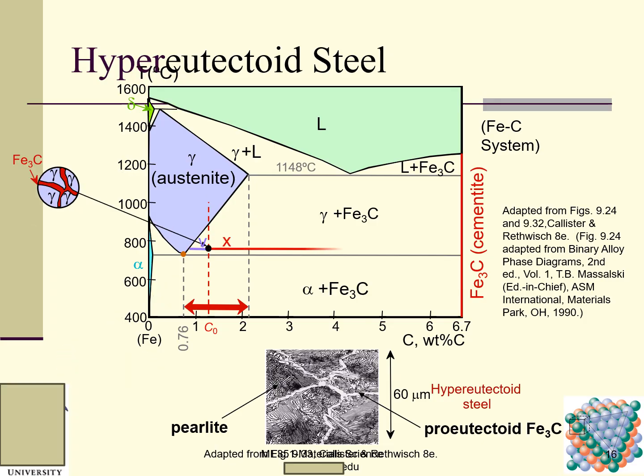And so what we want to do is the weight percentage calculation, and we use the same lever rule here. So you can use this equation to calculate. The gamma is x, right? The numerator is x. We need to be very, very careful. For this point, we have pearlite along with these branches, which is gamma.